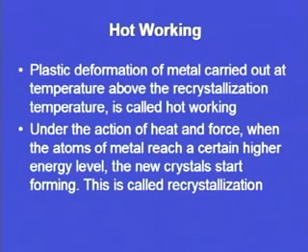Now, as the temperature is elevated above the recrystallization temperature, under the action of heat and force, whenever the atoms of a metal reach a certain higher energy level, new crystals start forming. This is called recrystallization. So, we have seen that the recrystallization temperature is a limiting factor to distinguish between hot working and cold working. What is recrystallization?